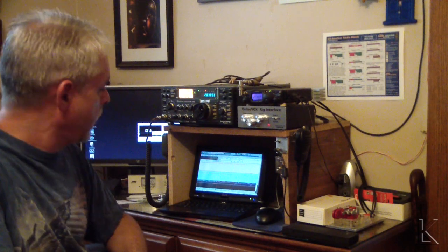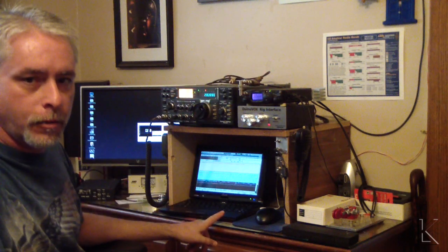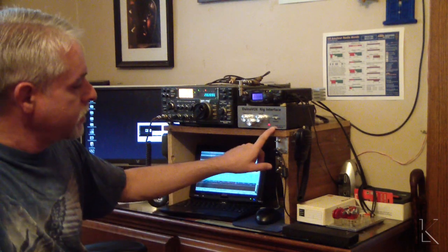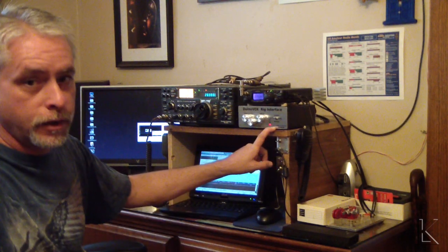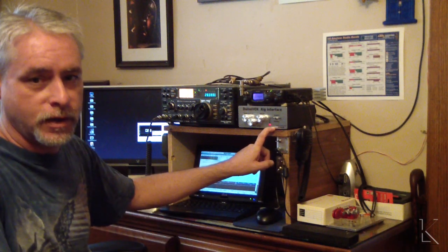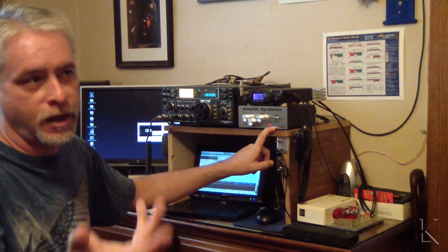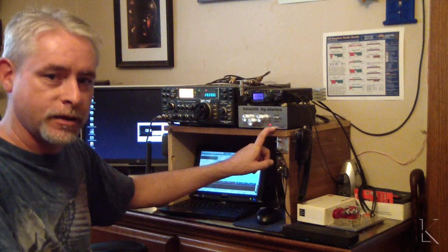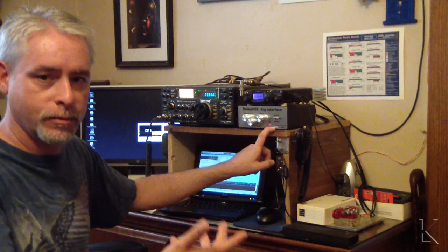Okay, demo time. I have the DuinoVOX hooked up to my little Yaesu FT817. Down here on the netbook, I have FL Digi running. I'm going to be capturing its window and hopefully be able to show you what I'm doing there. And first we'll talk about how you configure it. When you plug the DuinoVOX in to your computer, its audio dongle, whichever one you chose, will show up as an audio device. And then you go into your software, FL Digi, Ham Radio Deluxe, whatever program you're running, and choose that device as your audio capture and playback.